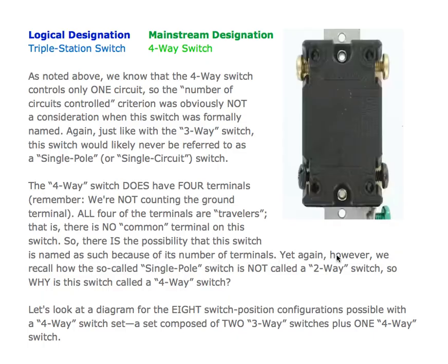Yet again, however, we recall how the so-called single pole switch is not called a 2-way switch. So why is this switch called a 4-way switch? Let's look at a diagram for the 8 switch position configurations possible with a 4-way switch set. A set composed of 2 3-way switches plus 1 4-way switch, okay?